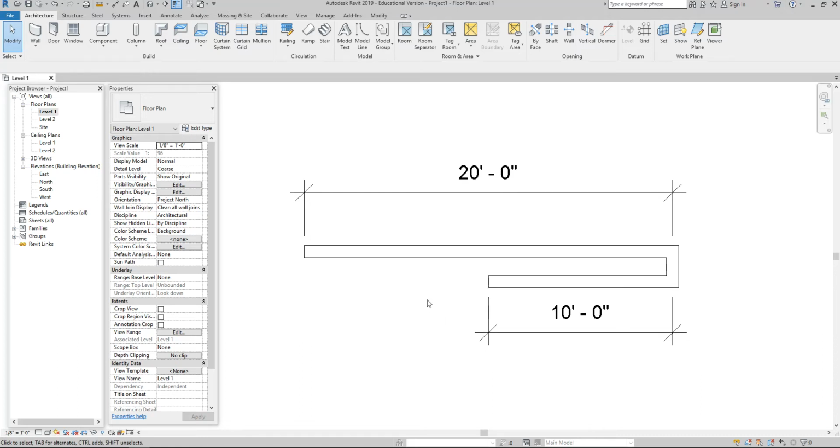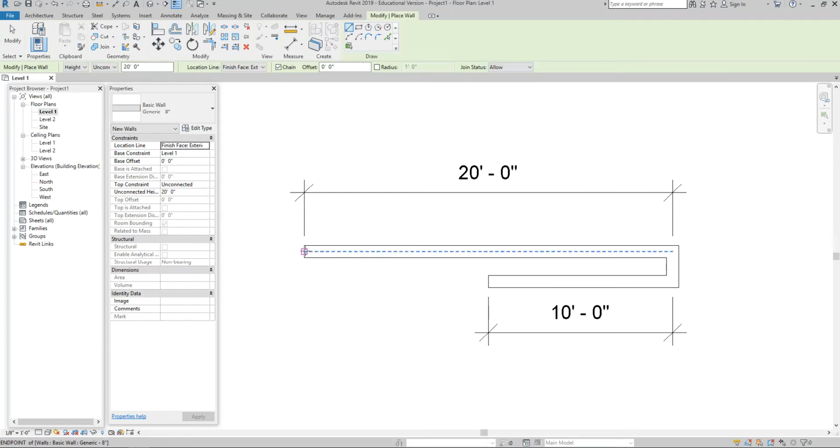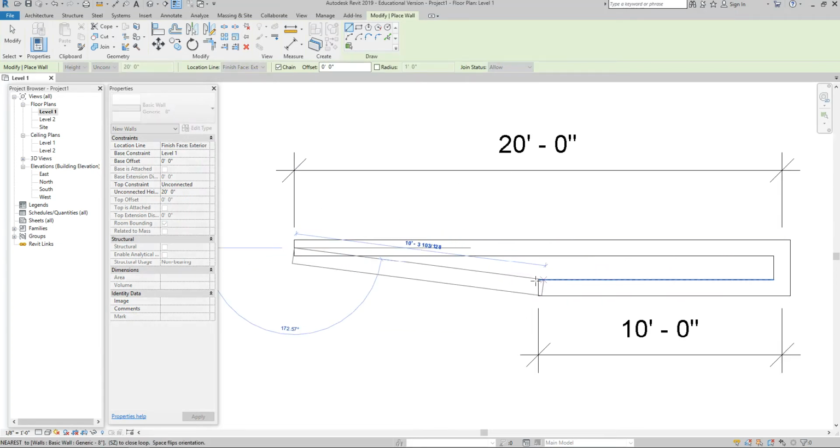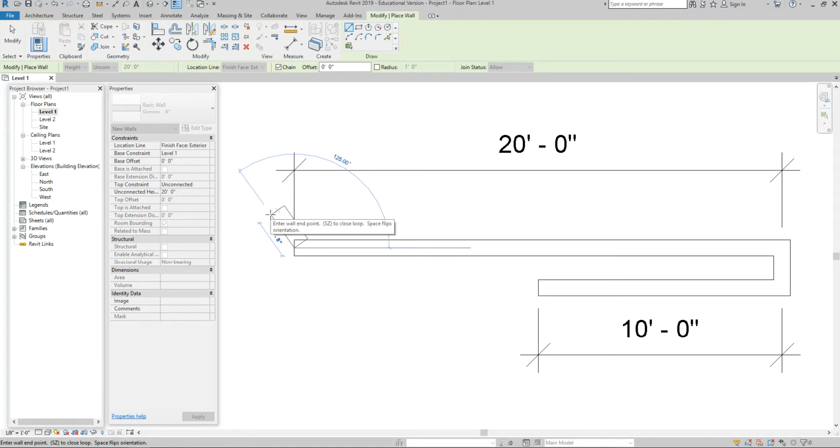So that is going to be our first drawing aid, our temporary dimensions, and they pop up everywhere, right? When I first started using Revit, I was like, oh, these are great. I love these temporary dimensions. They help me visualize. They help me draw things without having to type stuff in. They are wonderful. And then as I started using them more, I started thinking they're everywhere, and I can't differentiate one from another. You get to a point where there's so many popping up everywhere that it's almost like they are not functional for you sometimes. But in general, they're pretty okay.